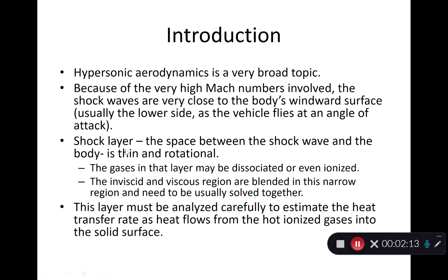So the region of the shock wave and the region behind the shock layer must be carefully analyzed to estimate what's going on in the boundary layer over the body, how much skin friction it is generating, how much heat it is generating, how much of that heat is flowing into the body surface. So this is very, very important.